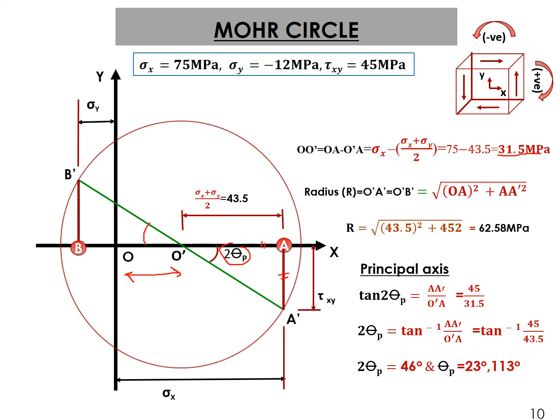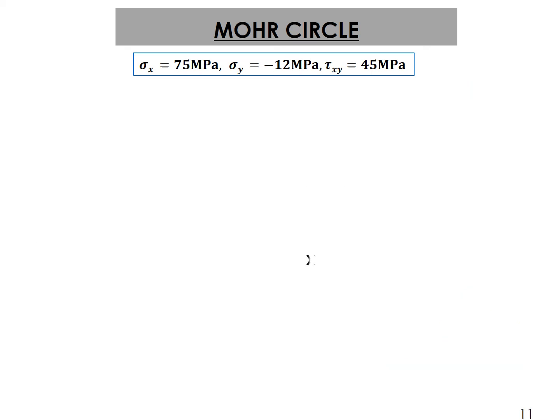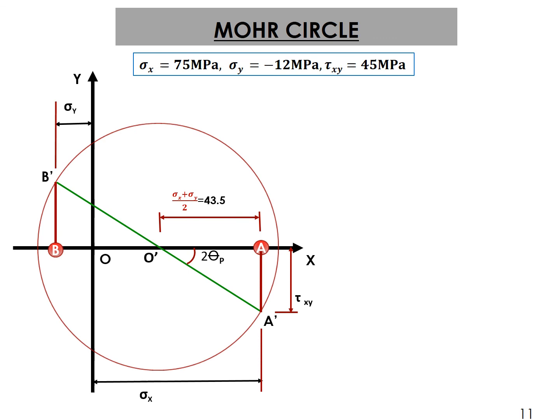Now what about next? Next is the principal stress. So let's see how to find that. First, again draw the basic Mohr circle. This is the basic Mohr circle. Now on this Mohr circle, which line gives you principal stress? From the origin, the farthest point, as I told you, is this point. This is the farthest point. It will give you sigma max. And the other point will give you sigma y. Two extremes you have to cover. This blue line gives you sigma max, that is OP.